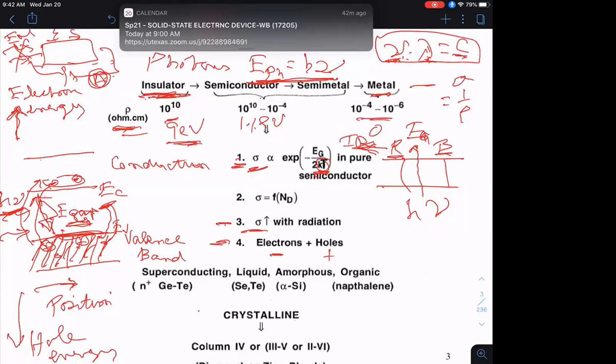So for example, we'll see in chapter 8 that not only can you absorb photons and create electron hole pairs in a photodiode, you can also bias a PN junction, inject electrons and holes, and if these electrons recombine with the holes, they'll give off light, and that's what you have in a light emitting diode or a laser, okay?